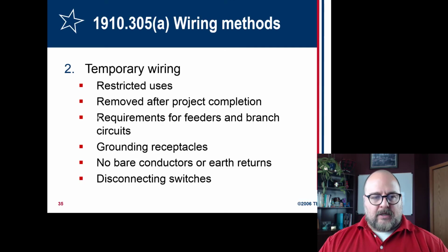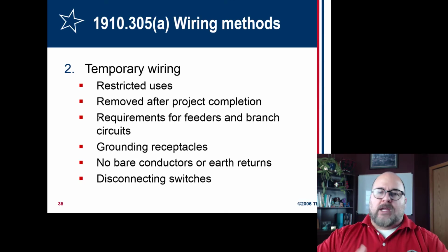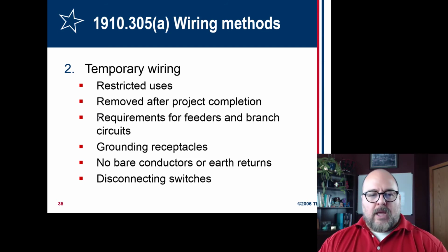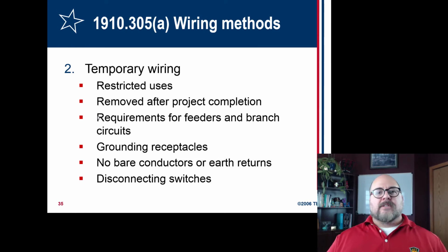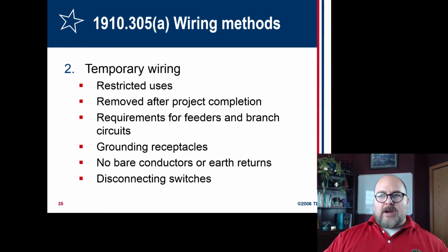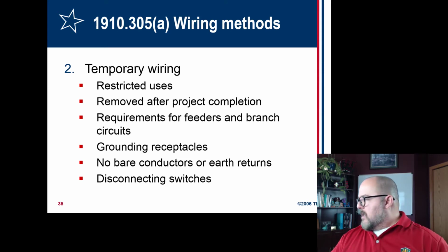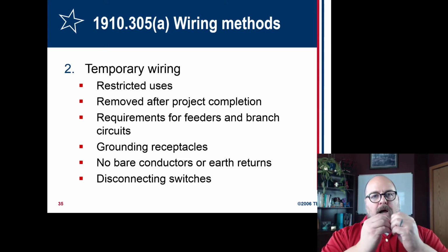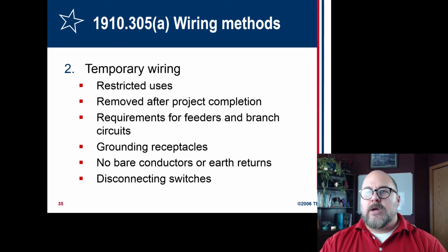All right, so we're in 305, and I'm going too long, I apologize. Temporary wiring, extension cords, typically. Not favored because it's exposed. It's an exposed wire. It doesn't take much to pinch a line, and then you have exposed copper.